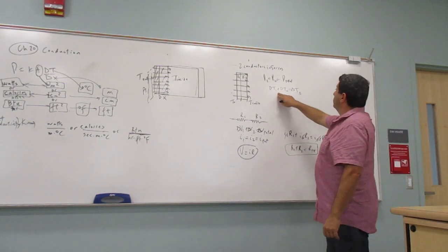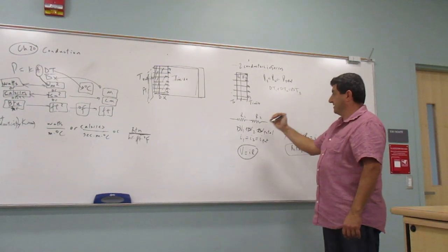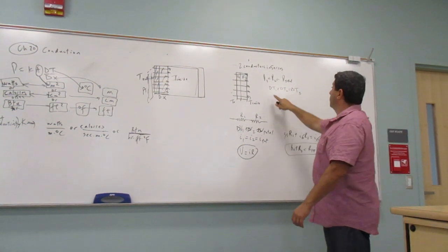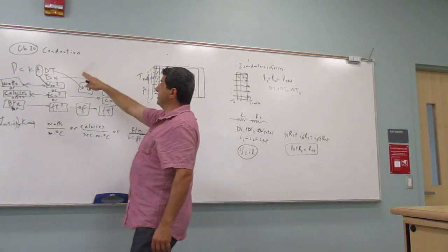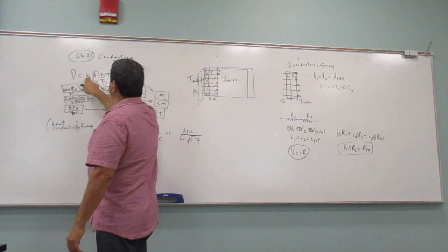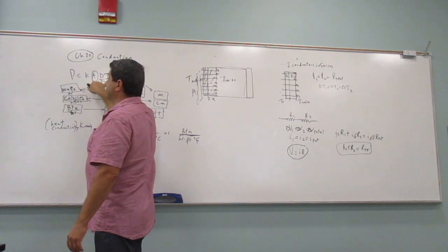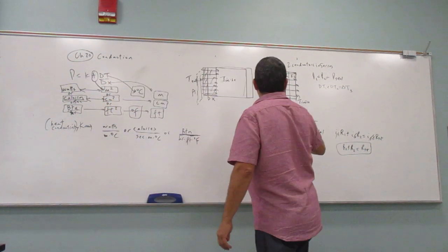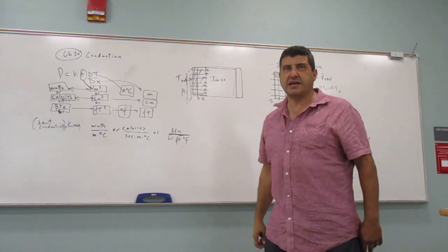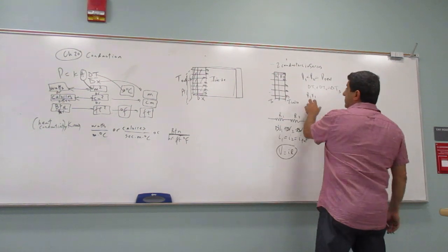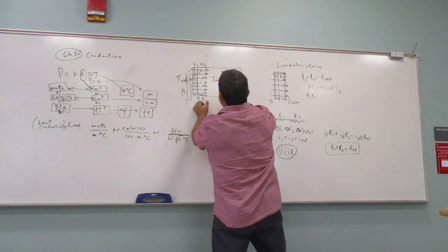So therefore, this is definitely behaving like voltage, you see? Then after you determine this, you use the relationship between delta T and P. So delta T1 is gonna be what? P1 times X1, right? Instead of writing delta X1, I'm just gonna write X1. So X1 is gonna be the thickness of this one right here. This is X2.